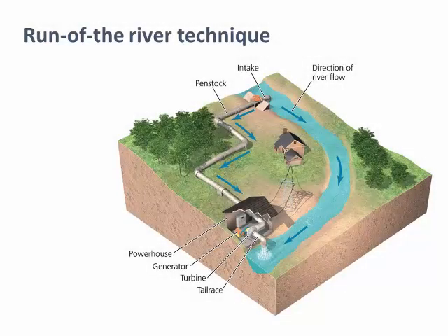The run-of-river approach generates electricity without disrupting the river's flow. Water is diverted from the river via a pipe or channel. The water flows through a powerhouse, which contains a generator and turbine, and then the water is returned to the river. This method is useful in remote areas away from electric grids. The downside of this method is that the electricity generated is less reliable because you can't guarantee reliable water flow. The benefit of this technique is that it minimizes impacts that come with damming a river. For example, the run-of-the-river approach doesn't alter existing flow or water levels.